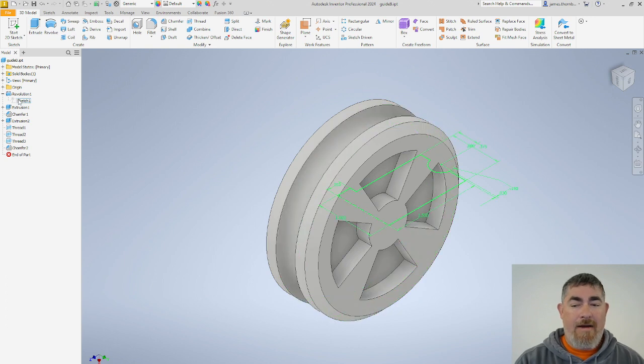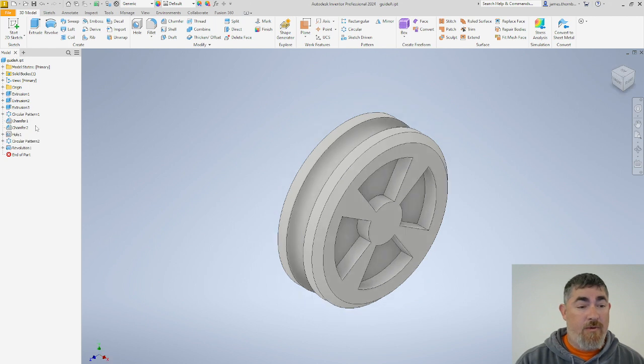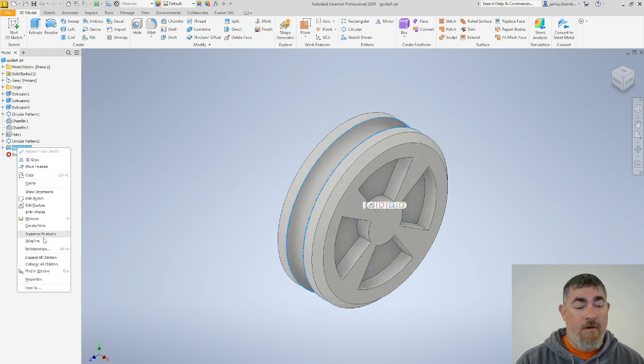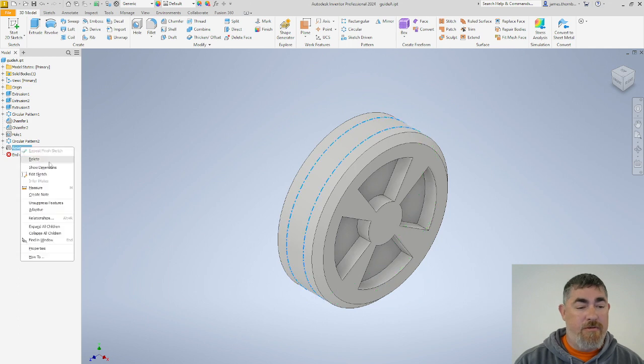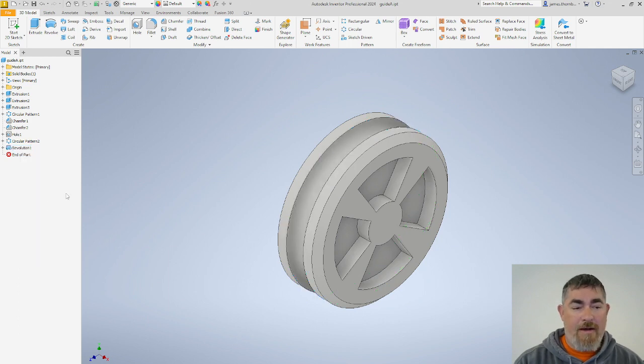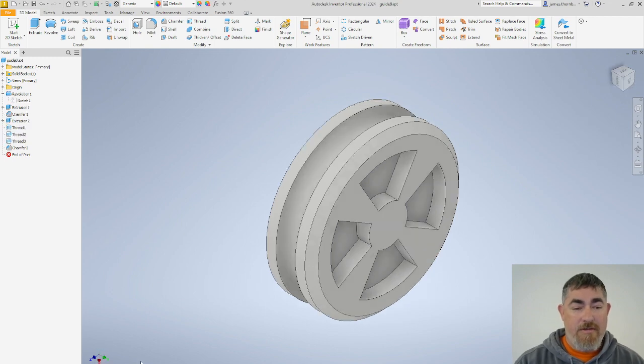Now we have to go back and edit that sketch, redefine it, all that stuff. If we're on this one, where that cut is here, we can just suppress that feature and then turn on another one that's got a different shape, or add a new feature to that. And so by having them split up, it gives us a little bit better ability to make changes.